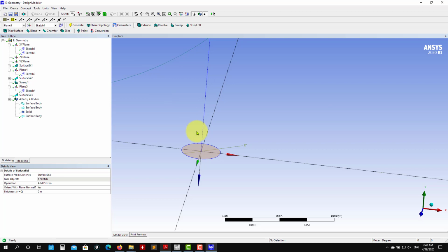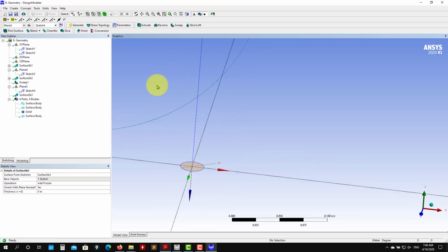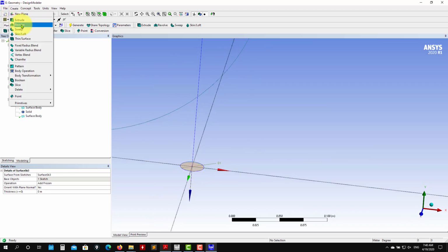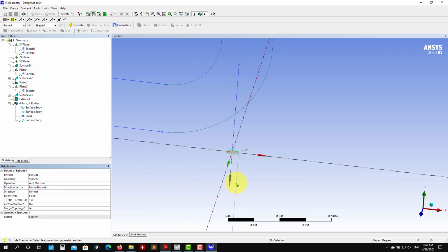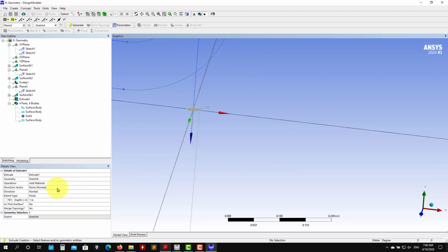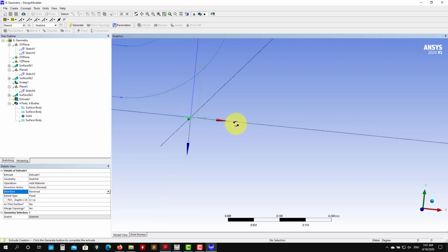add frozen, generate, and you have the surface, and then you have to do two actions, either the sweep, okay, or this normal extrusion. So the sweep will select this face and follow this line. The normal extrusion is something linear, so you select the face and then give a distance. So see that here it is pointing in this direction, so let me change this one. See here, you see it, so you can reverse the direction here, direction, reverse, and you have it there.